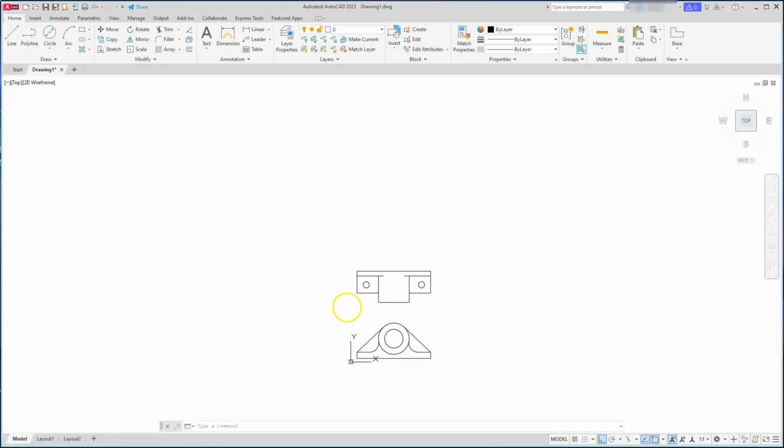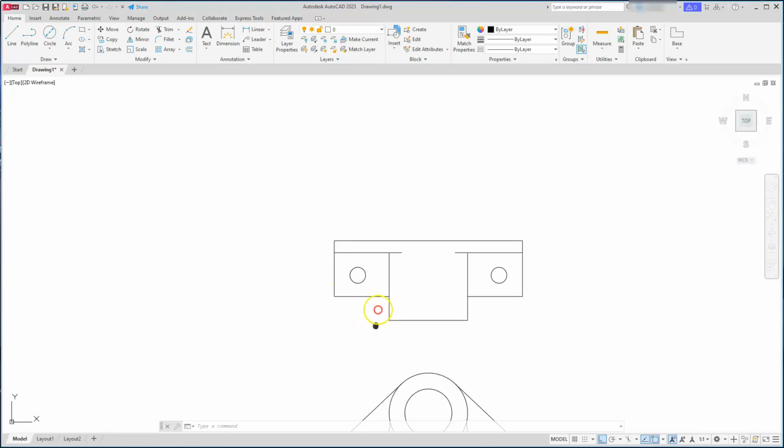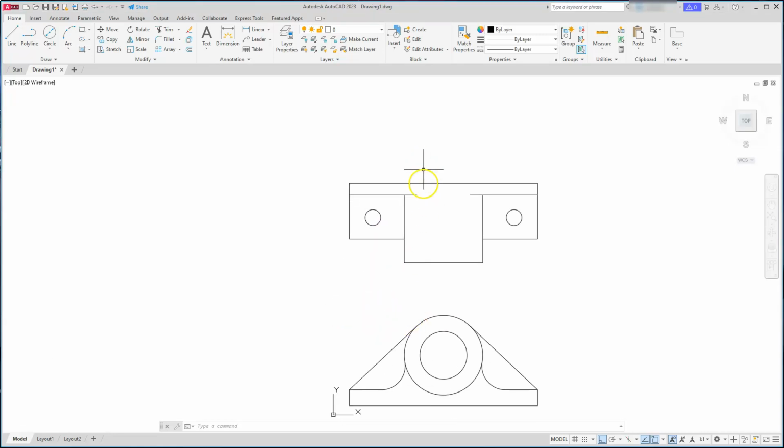Okay, so one of the other things I do notice is that I can go ahead and put the hidden lines in here, and then whenever I go to use my title block, I can go ahead and convert them to the right thing. But at this point, it's probably okay if I didn't want to include the hidden lines, especially for this part down here. So I'll save that for whenever I put the title block in, mainly because that will have the center lines and hidden lines and all of those layers that I need.